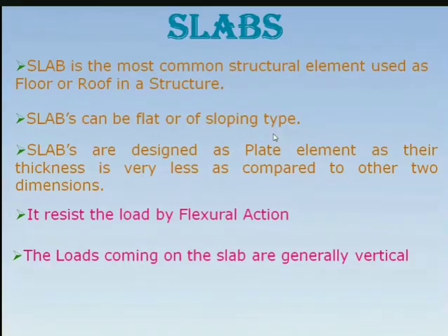live load. So for loading, we refer to the IS 875 code books. IS 875 part 1, part 2, part 3 for live load, dead load, seismic load, wind load, etc. So remember the code book for loading: we refer to IS 875 parts 1, 2, 3, 4 for your loadings.